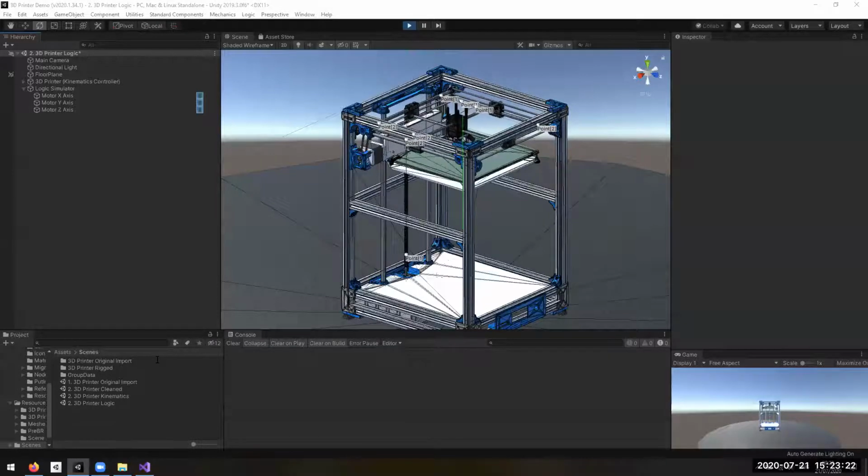The question: has this model been imported from industrial CAD/CAM diagrams directly without any modifications? No, you can use the Pixyz plugin, also available in the Asset Store of Unity, to import all sorts of CAD models. And the plugin will optimize the model so it can be used in Unity. Otherwise, it would be too big to handle in Unity, of course. We can directly import DAE files, however. Yeah, thank you. That's the one exception.